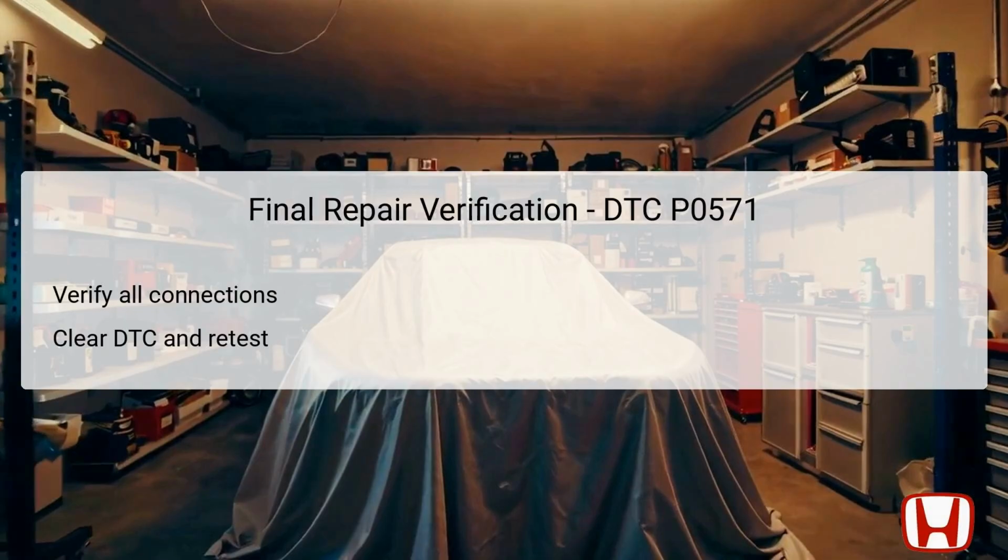Upon completing all the necessary repairs and replacements related to DTC P0571, it's imperative to verify that all connections are secure and functional. This final verification step ensures that the brake pedal system operates as intended and the issue has been fully resolved. Once all checks are satisfactory, the technician should proceed to clear the DTC from the vehicle's memory and conduct a retest drive to observe the braking system under operational conditions.